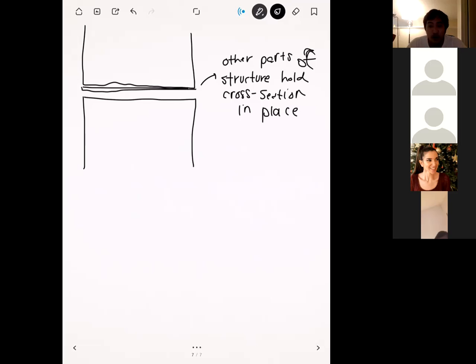Right? Okay, and so now let's talk about the other main way that you can make a big reduction in cost, and that's through symmetry. All right, and so we've already talked about symmetry, and I think everyone's familiar with this, but symmetry is basically a technique that you can use to cut your model at certain locations, and only do basically half the work. Okay.